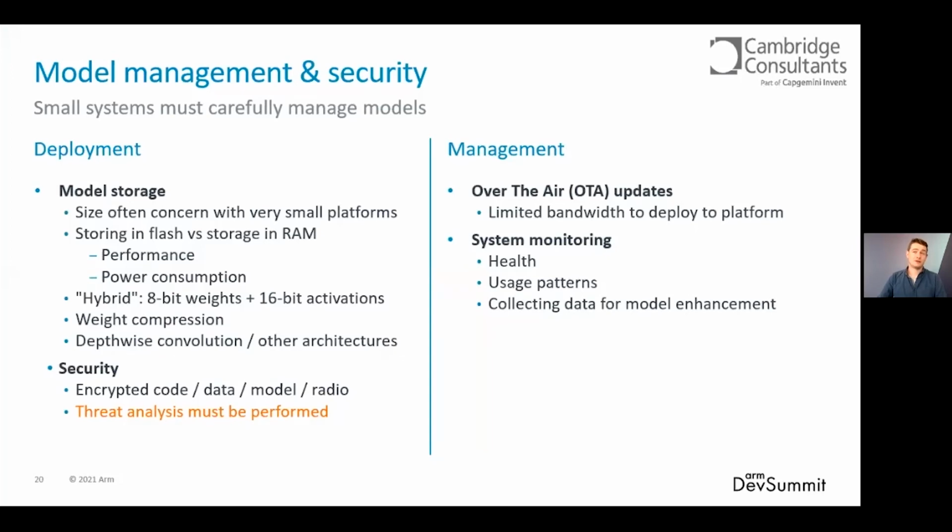For many deployments, the neural network can often be the largest use of storage on a device. To give an indication of scale, we have recently deployed a model to production weighing in at 64 kilobytes on a device with just 128 kilobytes of flash memory. In embedded devices, accessing data such as neural network models stored in flash instead of static RAM usually comes with a performance and energy penalty. However, the trade-off is that the cost of flash is a lot lower. For larger devices with dynamic RAM, a similar trade-off can be applied between dynamic RAM and static RAM.